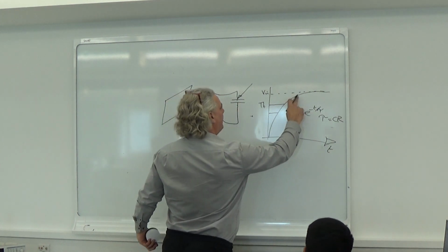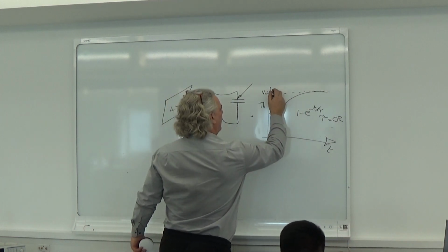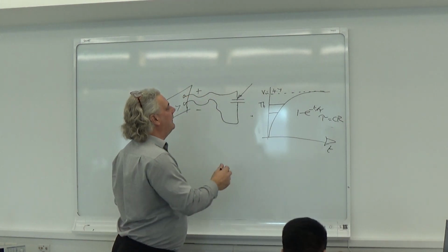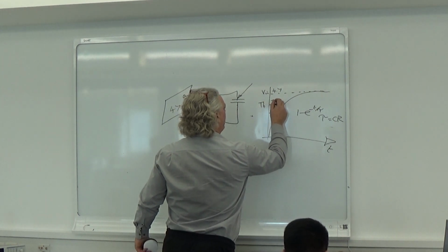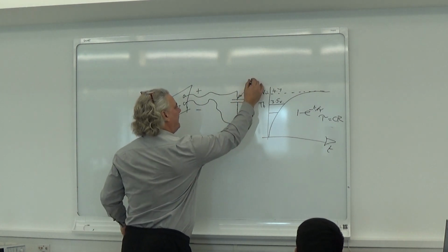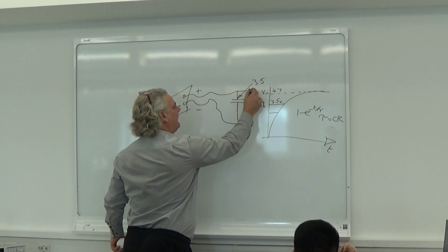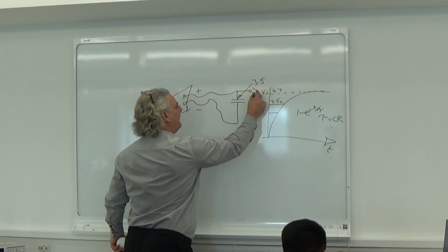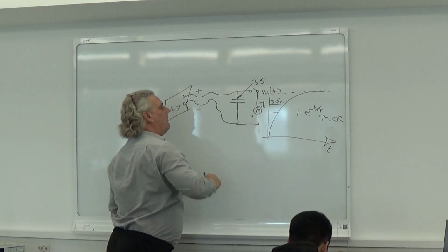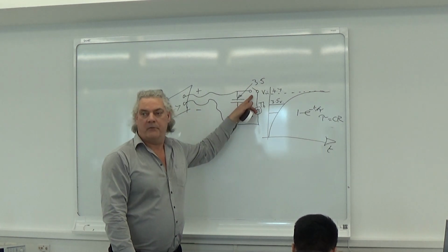So I charge up and say my V in is 4.7 or something like that. So I'm heading towards 4.7. My circuit has been designed, say, for 3.5 volts. So when this capacitor reaches 3.5 volts, I want it to operate a switch, so it's going to close that switch, which is going through a motor, and then once the voltage has dropped down, the motor is going to be turned off because the switch is going to open again.